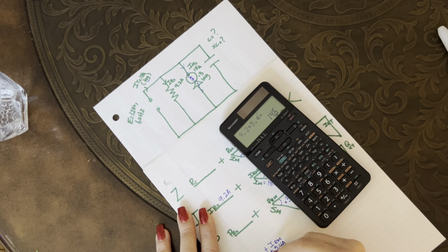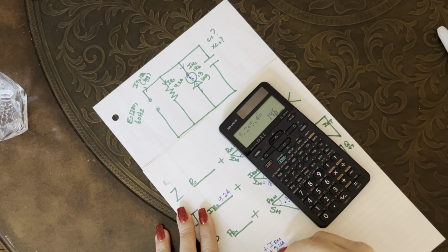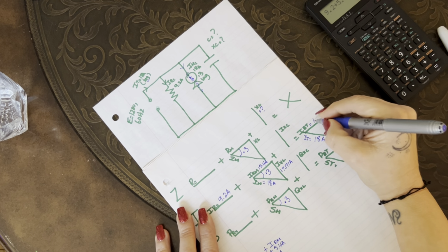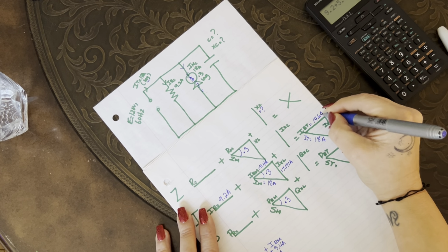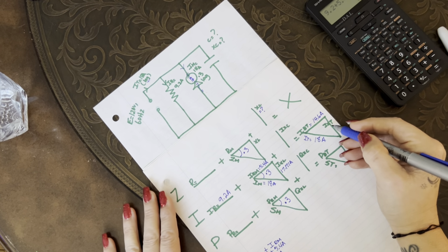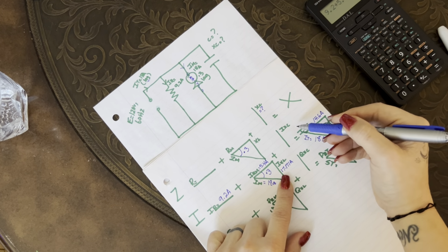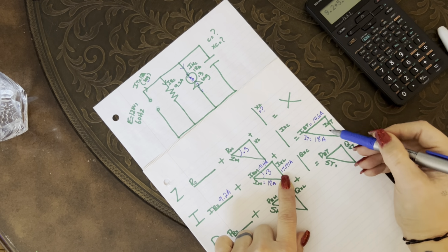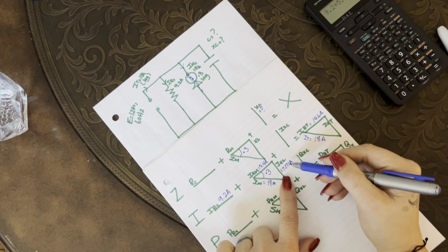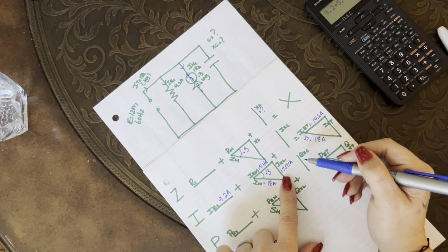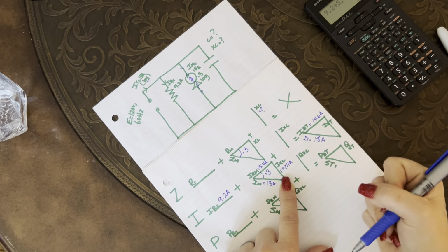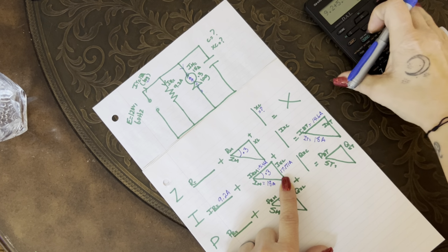So that's 14.6 amps. So that then would get populated in the bottom part of my circuit total, 14.6 amps. So now I can find my IXT. IXT is the resultant between IXL and IXC. And I know that IXT is lagging, which indicates that my IXL is greater than my IXC, which is going to be very important when I'm working back to the capacitive reactance of the capacitor, right?